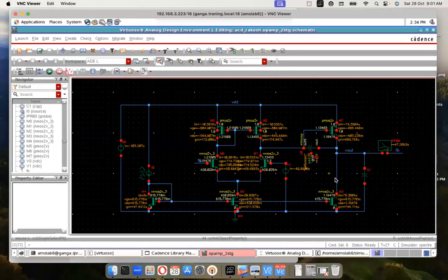Okay, so we do have some offsets here and there. That must be okay. Let's look at the DC gain that we could achieve. I clearly mentioned earlier that the DC gain cannot be directly calculated from our hand calculations, because we do not have an idea of the R out of the transistors. First stage out, we do not know the values. Second stage out, we do not have the values. Now, by our experience, you may come across some ballpark numbers, or you may estimate some numbers, but it may not really be accurate all the time. So for the time being, let's just keep it aside.